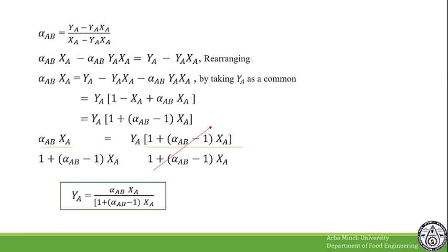So why do we need this equation? It is needed because this equation permits one to obtain the value of the mole fraction in the gas phase. When we solve problems, we may not be given the mole fraction in the gas phase, so we could use this yA value. If we have xA and the alpha value given in the equations, we could use this alpha value, find the yA value, and fill the table to draw the equilibrium curve.